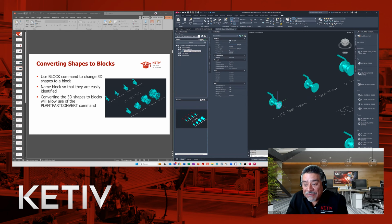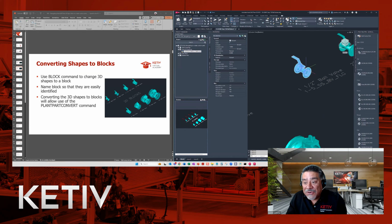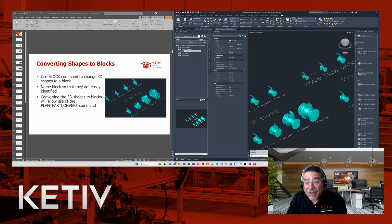So if I look at one of these and the components here, I have my surfaces here and everything. And then if I look over here, I've converted those into a block reference. So basically, I just went through my block command and selected each one of these and made it a block. Once I get into a block, then I can take the block and do a command within Plant to convert that to a part that I can add to a catalog. So let me show you that.